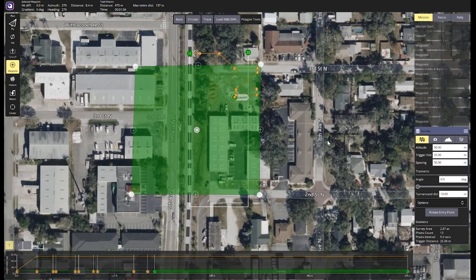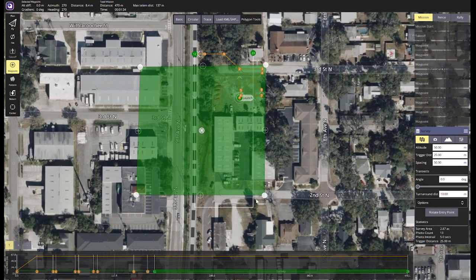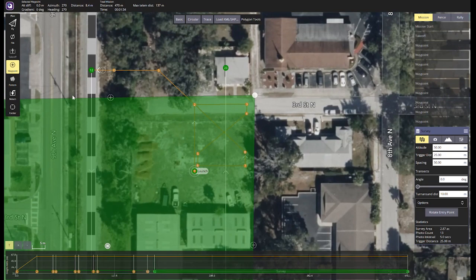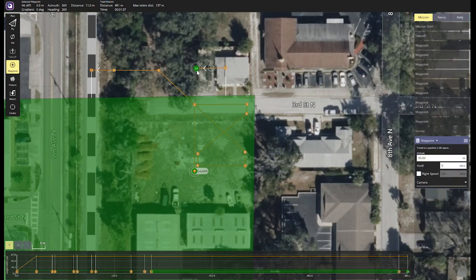After the exit waypoint of the survey grid, select the Waypoint tab on the left of the screen and create another figure 8 finalization comparable to the initial one. Remember to create a clean path using no acute angles.